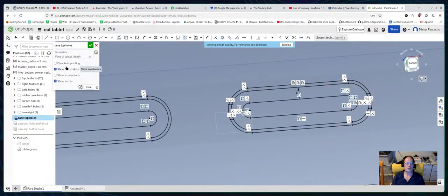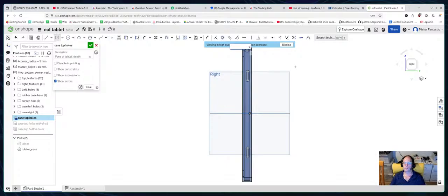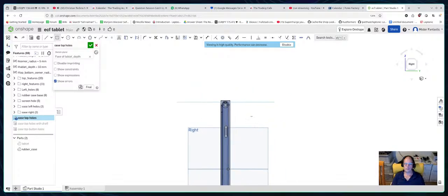Doing too much detail. Now we want to do the midpoint here. I mean, we could just do a line. Let's just use line and construction, and I'll go from that midpoint to this midpoint. Then we'll do a midpoint on that, which will give us the midpoint of the whole thing. And then we'll do a midpoint rectangle from there, which will go out here, and it'll be 4 mil wide. I just pressed some random button. Don't press the wrong buttons, me.